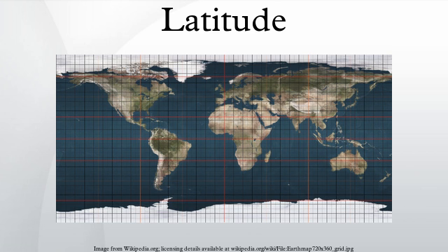Further, let β be the reduced latitude of P on the auxiliary ellipsoid. The set (u, β, λ) define the ellipsoidal coordinates. These coordinates are the natural choice in models of the gravity field for a uniform distribution of mass bounded by the reference ellipsoid. Coordinate conversions. The relations between the above coordinate systems, and also Cartesian coordinates, are not presented here.